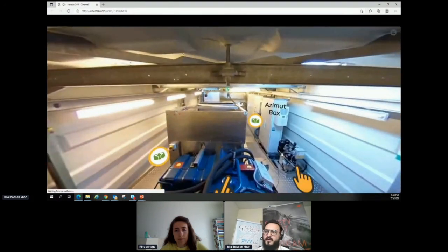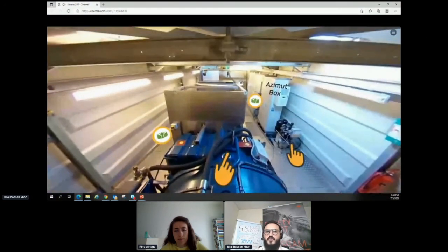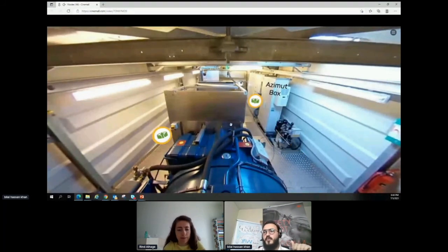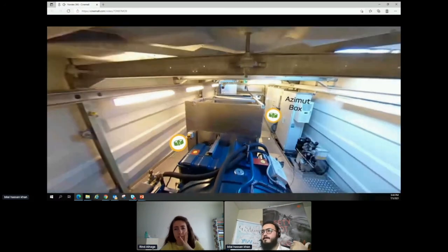And we have a hydraulic unit here. This unit, we are using just for the braking system of the rotor and also the braking system of the yawing. I will show you the yawing system during our animated video. So we are using this system only for two purposes here. In some new models, we have a hydraulic pitch system, so we are also using the hydraulic system to support moving the blade. But in this model, we are only using this hydraulic unit for the braking system on the rotor and also the yawing braking system.